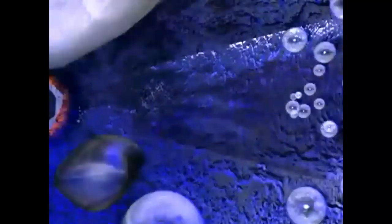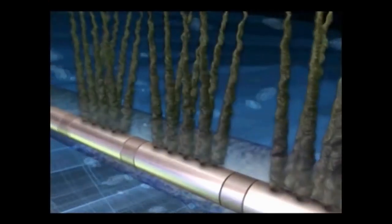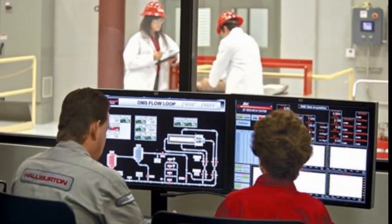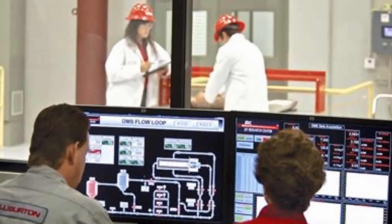Before first firing the guns, the hole is filled with salt water. This salt water is called water blanket or load brine. When the well is perforated, the water rushes out through the new perforations, killing the well and preventing a blowout. With the potential for further damaging the formation near the wellbore, using overbalanced conditions, the engineering team may decide to stop further perforations until the well has been prepared for production.